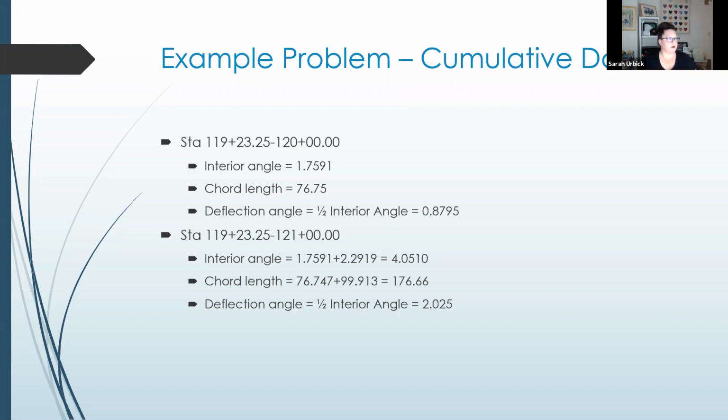So our interior angle at that first station, from 119 plus 23.25 over to 120, we calculated that angle just on the previous screen, 1.76 degrees.